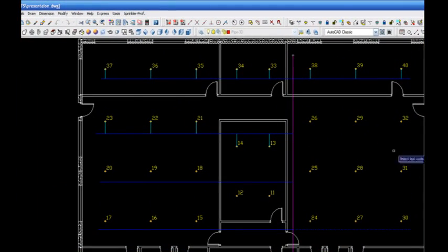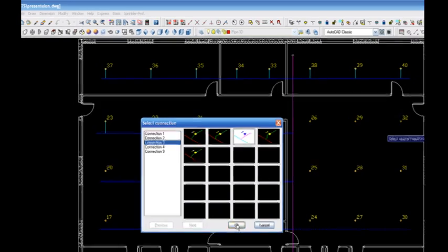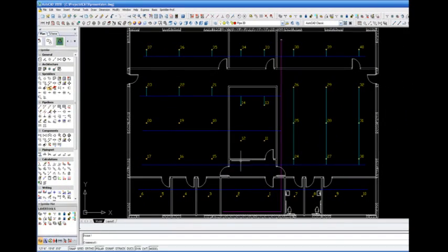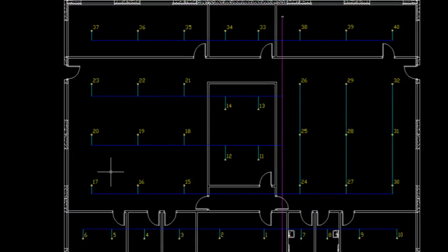The type of connection once more must be selected. We will select the third, which is a bottom outlet to the fire sprinkler head. Select OK, and the piping is placed on the drawing. After the layout is completed, you can delete the pipe ends that are not needed.